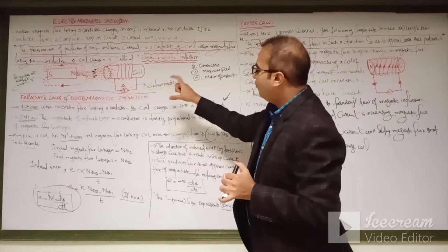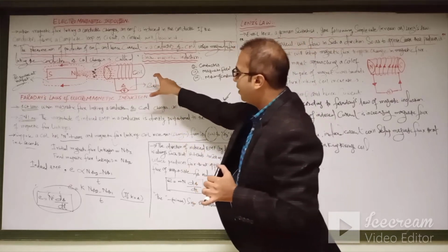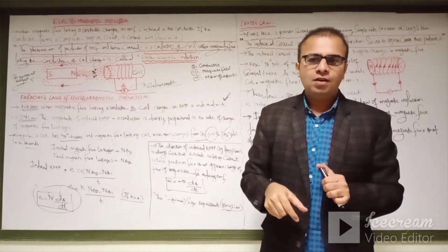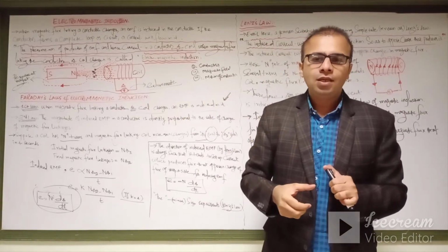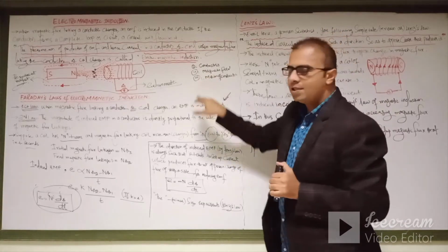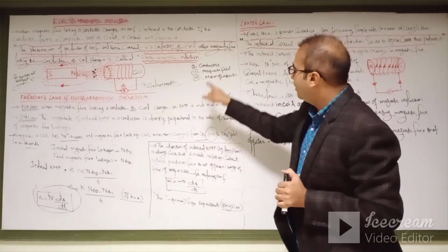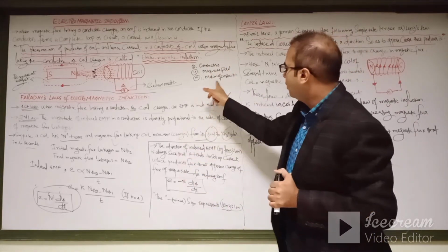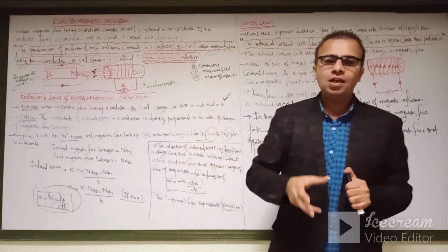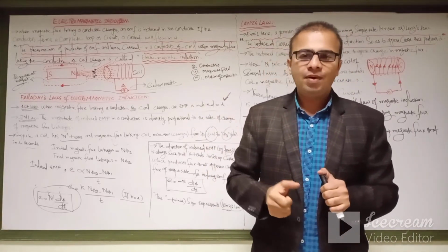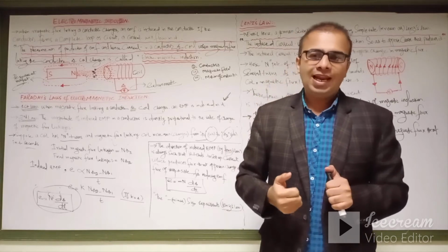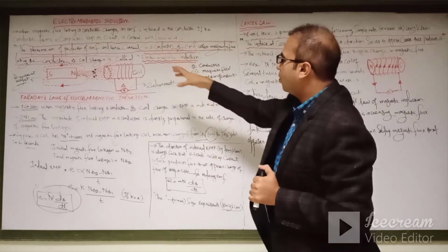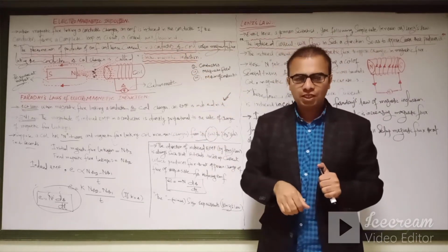Now, if we take the example of the permanent magnet and the coil, EMF can be induced in the coil. For this, we have to keep three essential things in mind: the conductor, the magnetic field as a coupling medium, and the motion of the conductor are the necessary requirements for the production of EMF in electrical machines. Okay, so this is the total concept regarding the electromagnetic induction process.